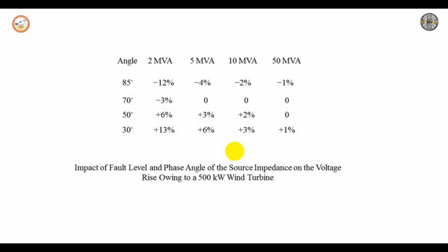This is because the minimum load occurs at different times of the day than the maximum production. This signifies that the daily variation of both the load and the production should be included, otherwise the hosting capacity can be strongly underestimated. The potential voltage rise owing to the large number of photovoltaic panels connected to this low voltage network has been calculated for a city in the UK.